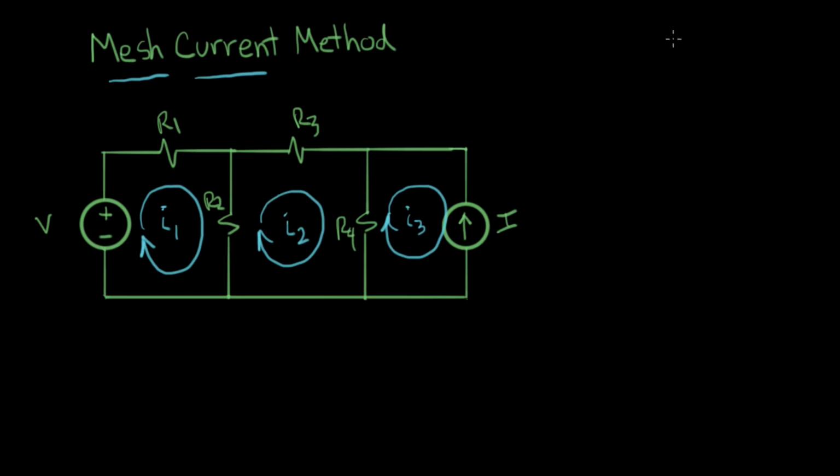Let me go over here and we'll redraw R2. Here's R2. And now I'll redraw the mesh current. So here we have a mesh current I1 going down like that. And we have a mesh current I2 like that. And I'll label the element current for R2. We'll call that IR2. Now what's going to happen, this is a really wonderful application of the principle of superposition. I1 and I2 superimpose inside R2 to create IR2.